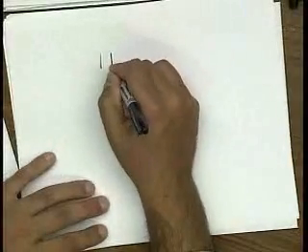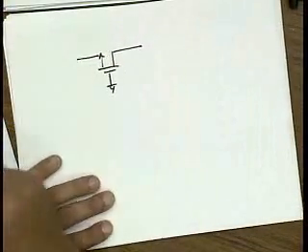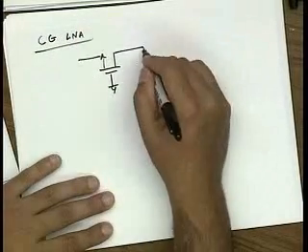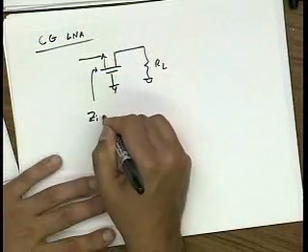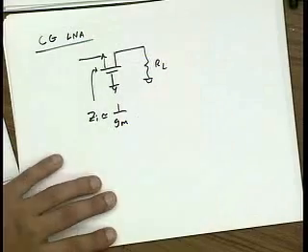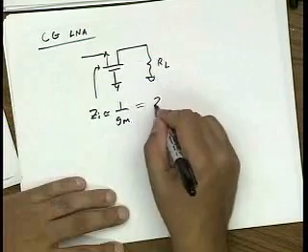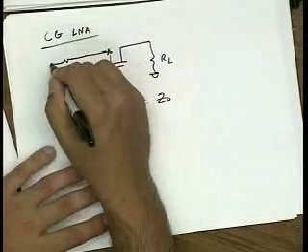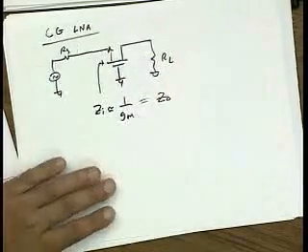Okay, well, another way to get matching from a transistor is to use a common gate device. So how about a common gate LNA? Again, common gate device is really nice because the input impedance is approximately 1 over gm at low frequencies, and I can basically design it so it's equal to Z0. Right, pretty simple. And then I connect RS, and I want to now calculate the noise figure.